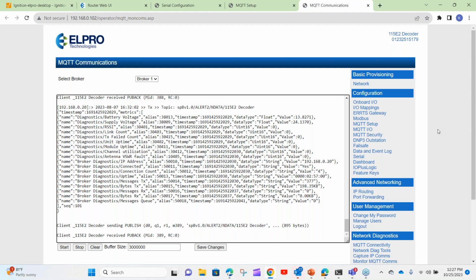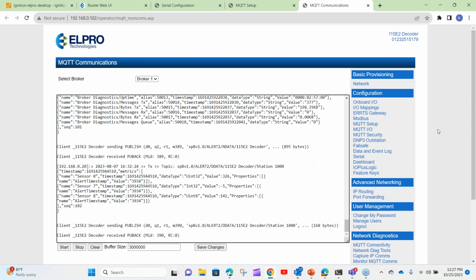And just recently, and I need to get back with a customer, they have the need for monitoring the level underneath the manhole. The problem that they have is that a manhole is made out of metal. They do make hard plastic ones, but for the metal one, if we created some kind of penetration where we have the antenna, and then add repeaters to repeat this signal remotely, we may have a solution for a customer.